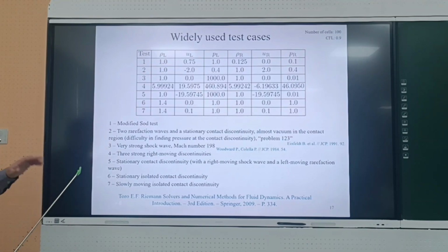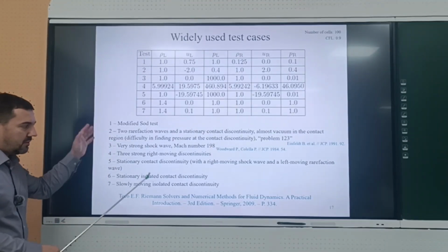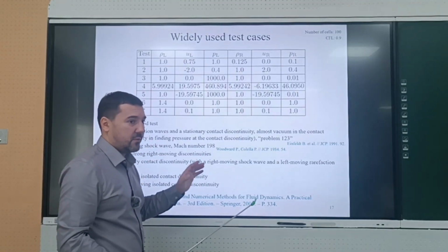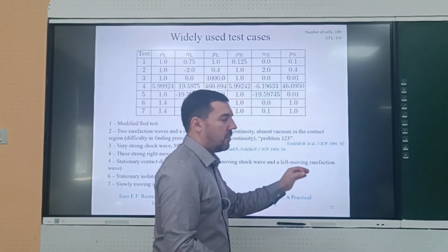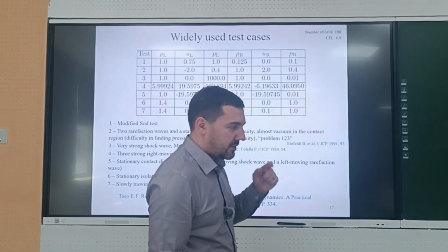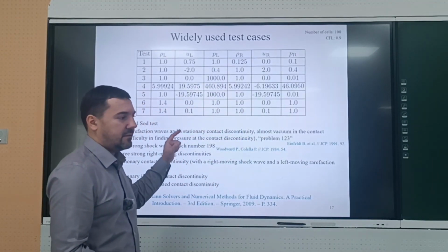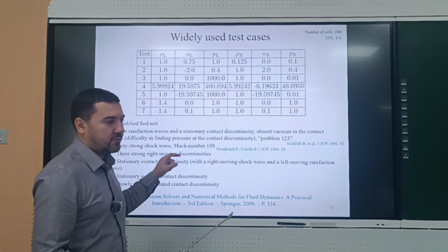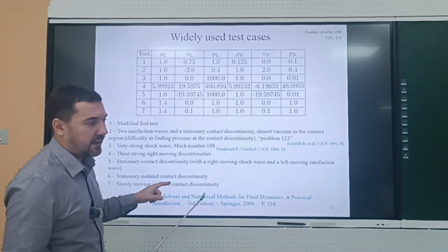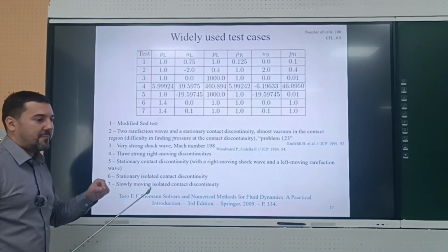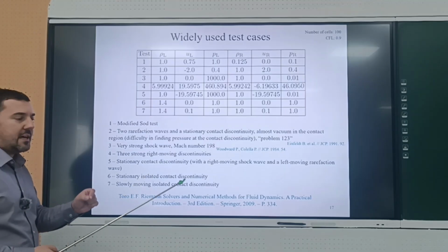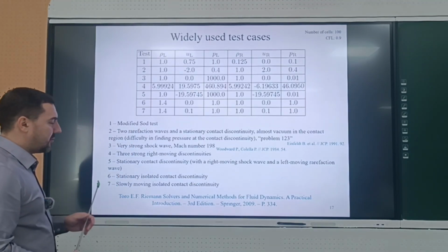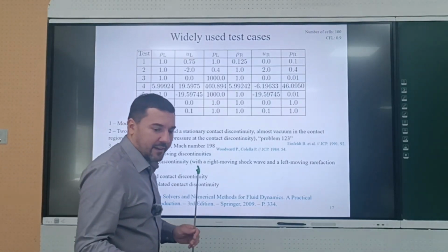For many methods, the advantages and disadvantages are known, and so I recommend you do this. For example, if you use software like OpenFOAM or Fluent, just ask yourself: can I check all these tests? Is my software able to compute them? And what parameters, what time step should I choose to do that? It can be very useful. And actually, it's necessary to do that.